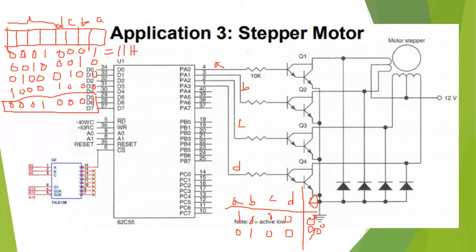As I said, here it will be 90 degree. Because you remember, if for example this is our rotor, this is for A, this is for B, this is for C and this is for D. When A phase is on, the rotor will be in the same axis as A. Then B is on, it jumps from here to this axis.